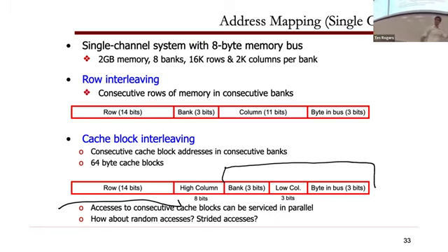Even with this bank level parallelism, you can of course do all the accesses of consecutive cache blocks at the same time. But for transferring to a CPU, GPU, anything else, you're still pin limited. So is the idea that there's some sort of burst transaction where you just assume increment, and every time you see a signal, you have the block immediately ready to go, and you just change the mux on the final output? Is that why it's faster?